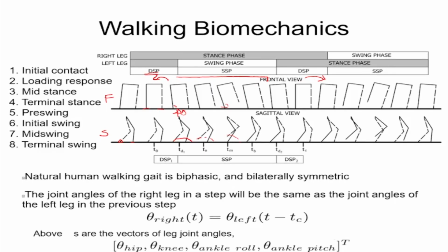If you look at these figures, this is basically called the gait diagram or the timing diagram. So we have a DSP, SSP, and a DSP. It basically means that the robot has to bend on one side, move its rear leg forward, and the body also moves forward, and that's how the system has locomotion, or moves from one point to another. There is of course no turning here. So this should be very clear in terms of the DSP, SSP, DSP, SSP again.